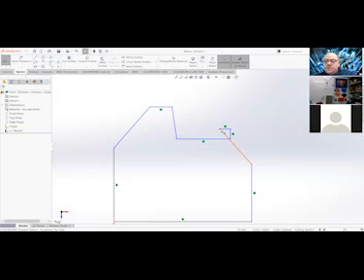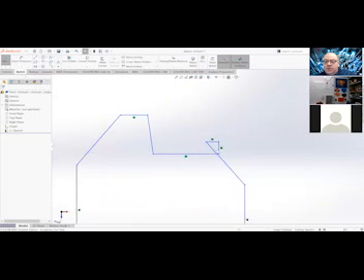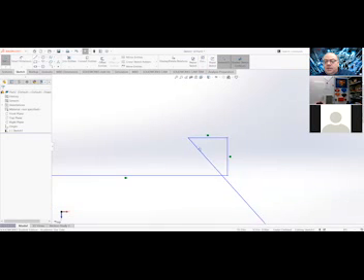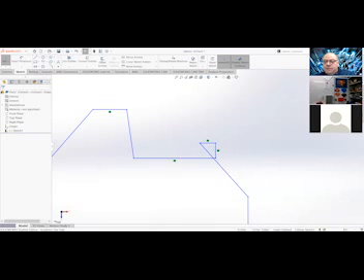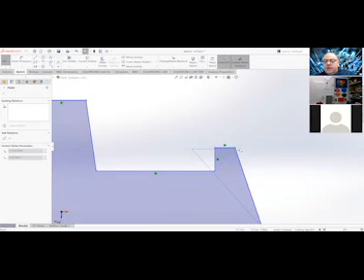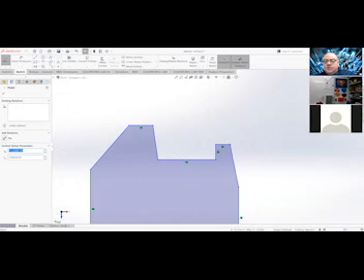If I grab this joint, this connector right here, and I'll zoom up on it. So I know this endpoint needs to go to this side so that I have the shape of my base drawing that we spent so much time drawing. If I grab that corner and just drag it over, notice I can untwist and I get my shaded area back. So that's what I'm going to do. I'm just going to slide this over so it's not twisted anymore.